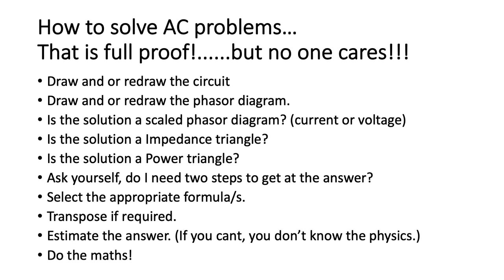Do the same for a phasor diagram. Even if you don't do the phasor diagram to scale to start with, draw the phasor diagram relationship. It'll get the picture in your head about which is leading, which is lagging, where everything is in relationship to each other, depending on whether it's a series or a parallel circuit.